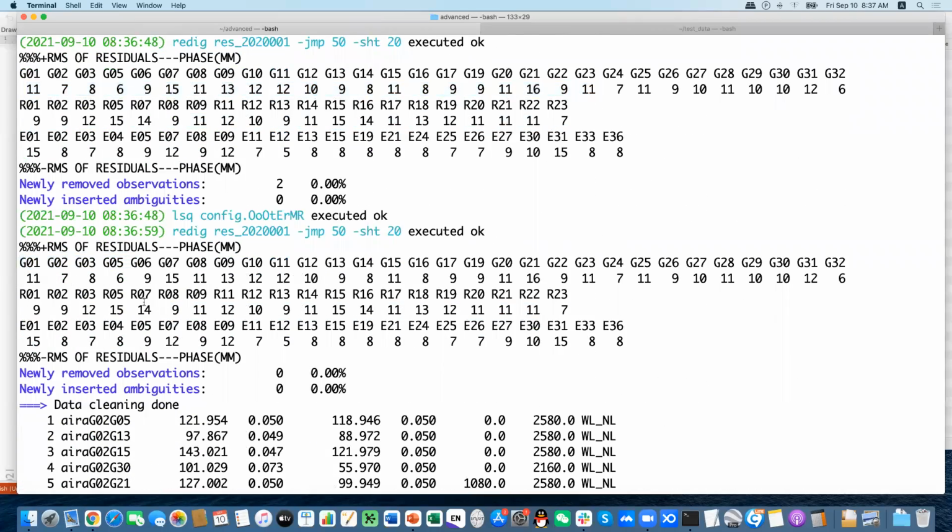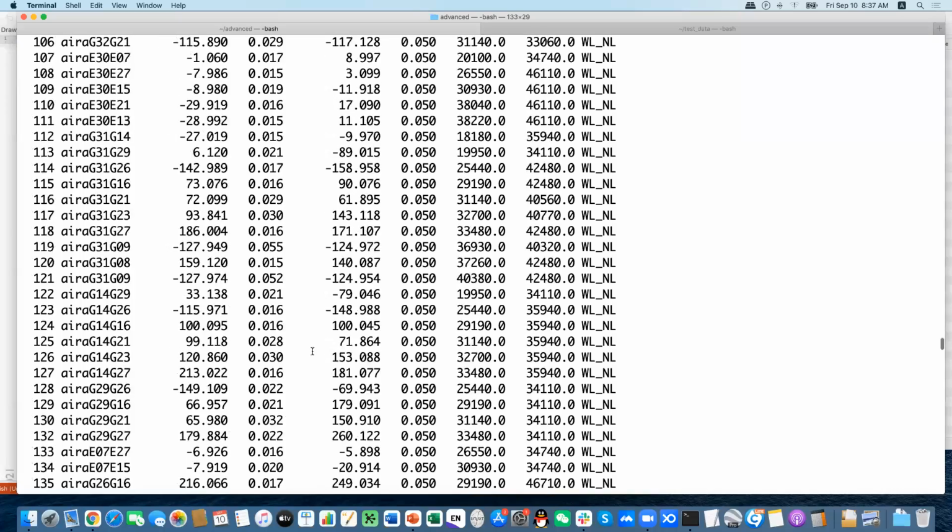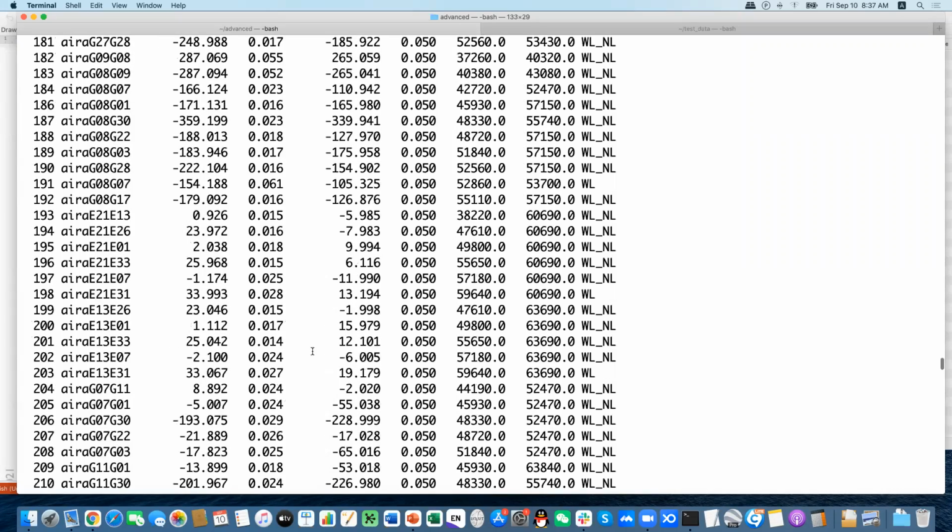The final iteration you see here, the 6 lines here, the residuals from GPS are similar to Galileo. Galileo is really good. So you can see their residuals are smaller than 1 centimeter, just a few millimeters. GLONASS is a little bit worse compared to GPS and Galileo, but more or less the same, not so large distance between the 3 constellations. All right, let's come to the second part, which is ambiguity fixing status.